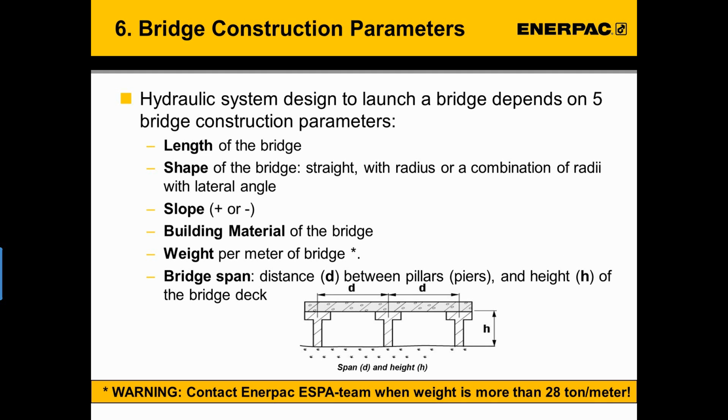Let us take a look at the elements which we need to analyze when considering which controlled hydraulic solutions to advise. There's the length of the bridge, the shape of the bridge. Is it straight? Does the design follow a radius? Or is there a combination of radii with lateral angle? The slope, uphill or downhill, the building material of the bridge, and the weight per meter of bridge.